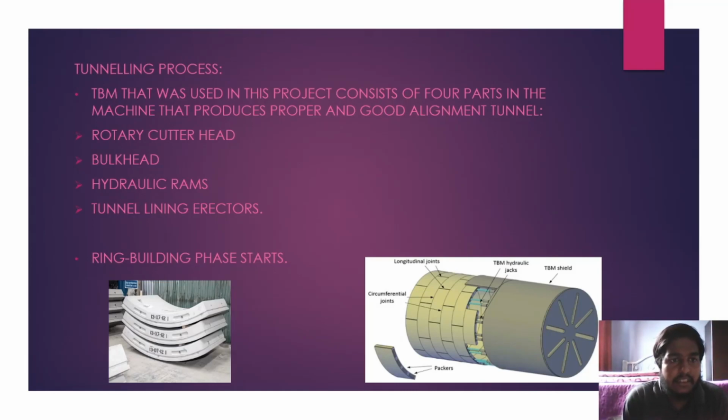The hydraulic cylinders are temporarily retracted in order to provide enough space for the new segment. The segments are positioned with millimeter precision and held in place by cylinders before being bolted into position. The conical keystone is put in from the front to complete the tunnel ring. The hydraulic cylinder is extended again to secure the segment into position.